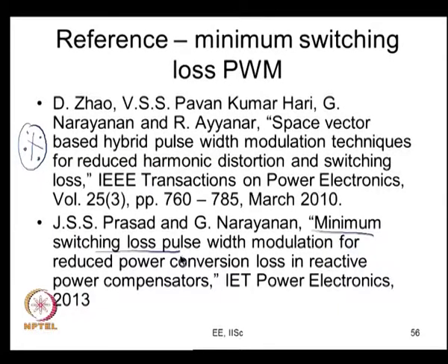And there is conduction loss also. If you look at the total power conversion loss, this paper reports that there is some 7 to 8% reduction in the total power conversion loss. That is what it reports, and this is for a specific application of reactive power compensation. So, you have these power losses evaluated here. Here also you have analysis and you have the experimental results, which are shown at a power level of a few kVA. Here it is shown at a power level like 100 to 150 kVA.